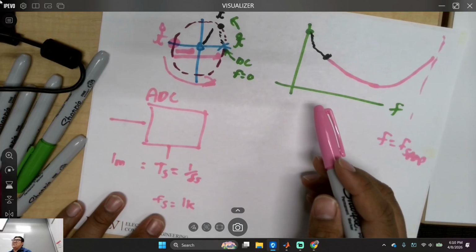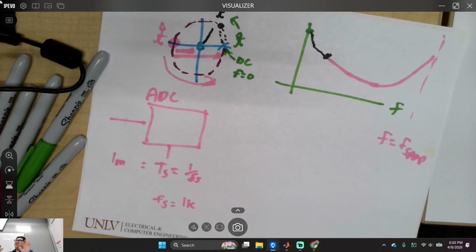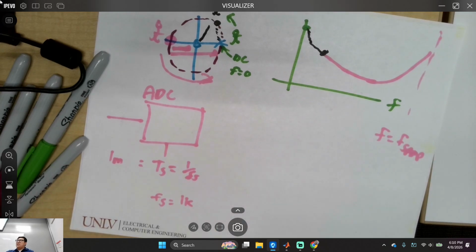Who knows what anti-aliasing is? Aliasing. Things that you're supposed to not be seeing, ghosting or something like that. Has anyone seen a tire on the freeway? You're driving super fast, and you see people's tires, and it looks like they're going forward, but there's a point where it stops and then starts going backwards, right? That's aliasing. It shouldn't be doing that because it's going so fast. It looks like a fake image or it's ghosting. So you apply an anti-aliasing filter so it looks like it's going forward.